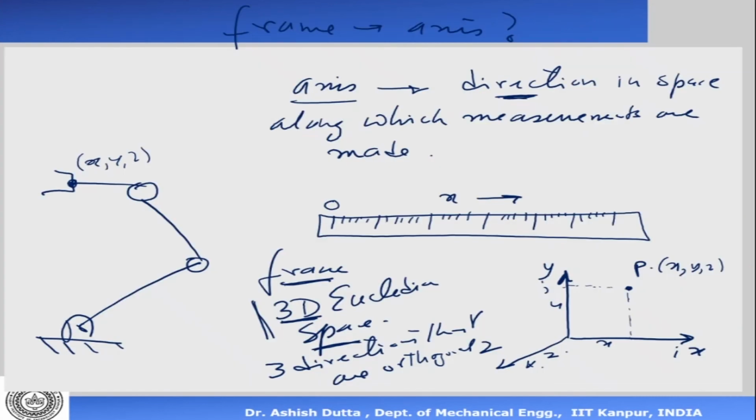Now if I think about that, I try to imagine, how did the last frame go there? Suppose I have a frame which is here. I can say that my z0 was here and z1 is here, x0 is here and x1 is here, and that is y0. These two have the origin at the same point. Now I have another frame there which is z2. This is my x2, and I have my y there, we don't draw the y. So x2, y2 and z2.